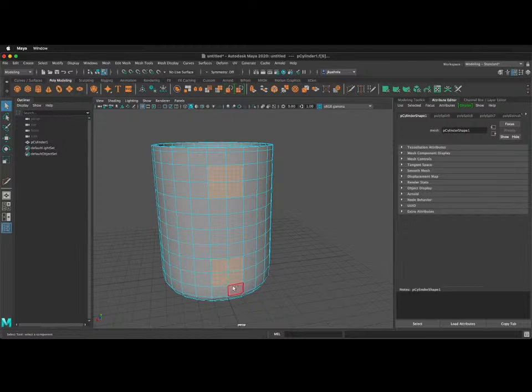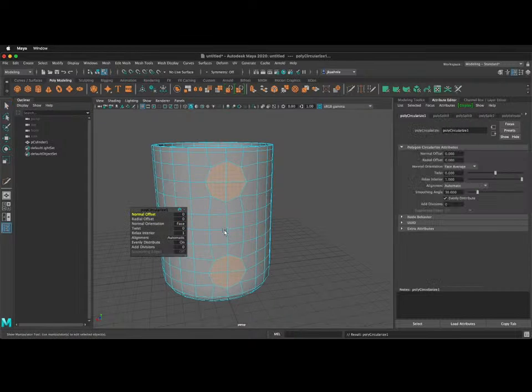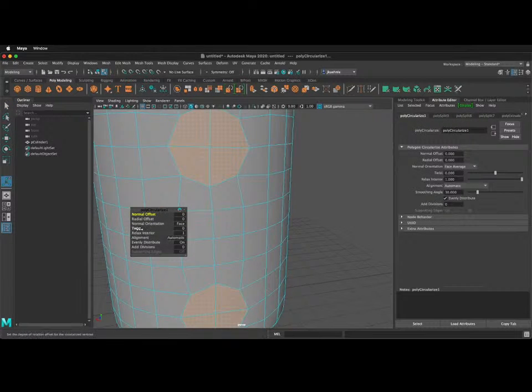And then notice how this axis, the Z axis, goes right through the middle. If I hold Shift and right-click, then I can circularize my components. They'll come in a little twisted, so we can use this twist command to just kind of even them out. About 2.2 at this size works, but your model may be different.